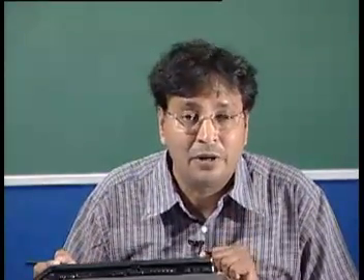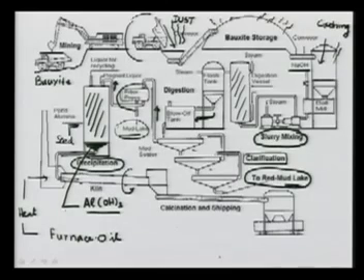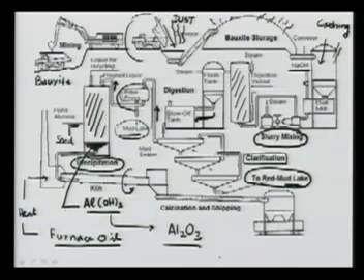Most of the time we don't use coal, because coal will make our alumina very impure. So what we use is generally, and again this varies from plant to plant, furnace oil or other cleaner fuel. In the kiln the heat is supplied, so aluminum hydroxide breaks down, or rather gets calcined, to Al2O3.